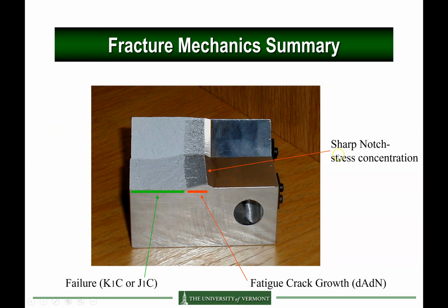Okay. So here's just a view of a compact tension specimen after the test. What is important to understand is that in the same test, we're actually conducting the crack initiation. So we have a notch. In fact, our specimen in lab number 6 will have a V notch here, a chevron notch, to properly initiate the crack. So there's a crack initiation, then we propagate in fatigue, here the red region, and then we stop the crack in fatigue and apply the monotonic load to break the specimen,